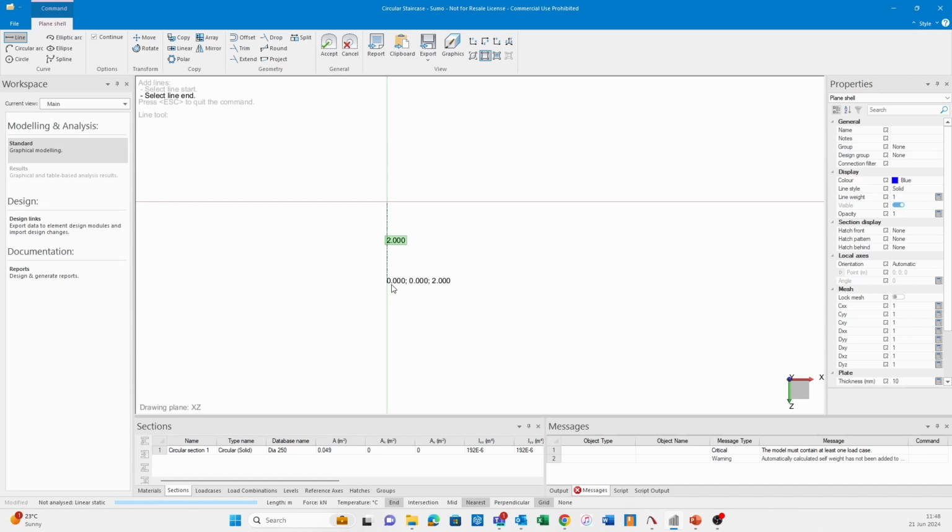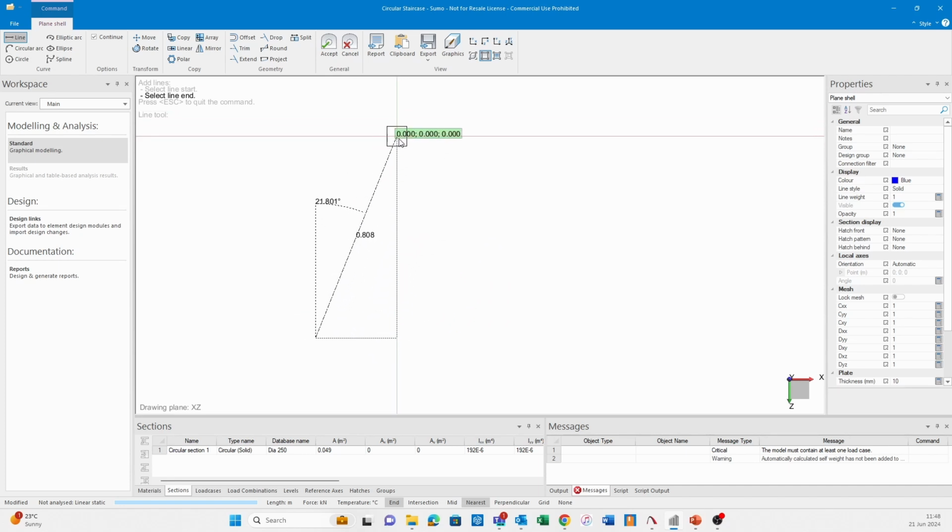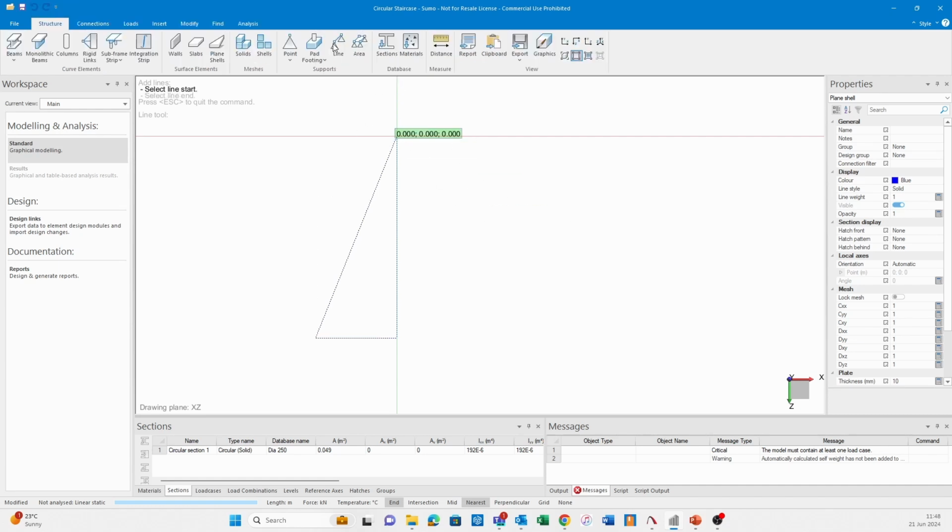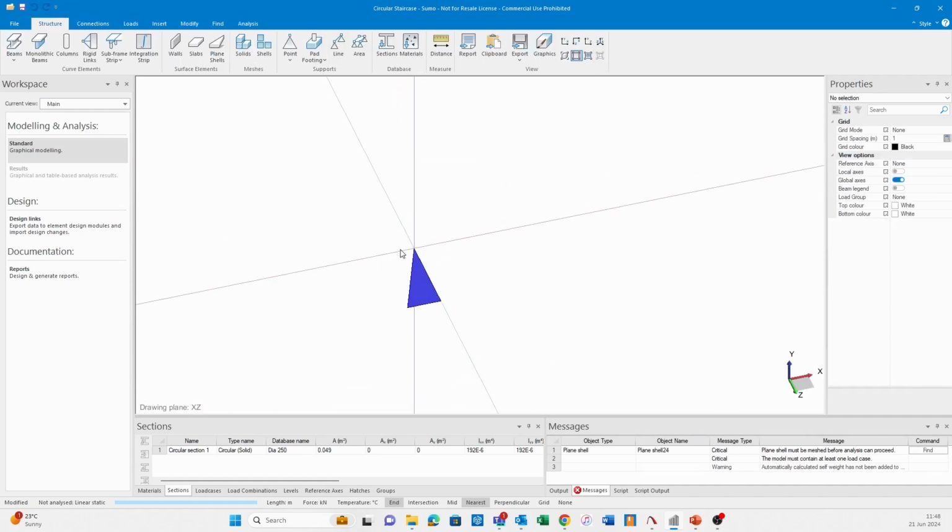And I'm going to make the step length 0.75 meters. Going to turn grid snapping off, and the step size or width is going to be 300 millimeters, so 0.3 meters. You can check there, I use tab to switch to the polar distance. Press tab again to switch to the polar angle, and I make that 0 degrees. And there you have a nice 90-degree line. And then I'm going to snap back to the start point and press enter. All right, there's my step.